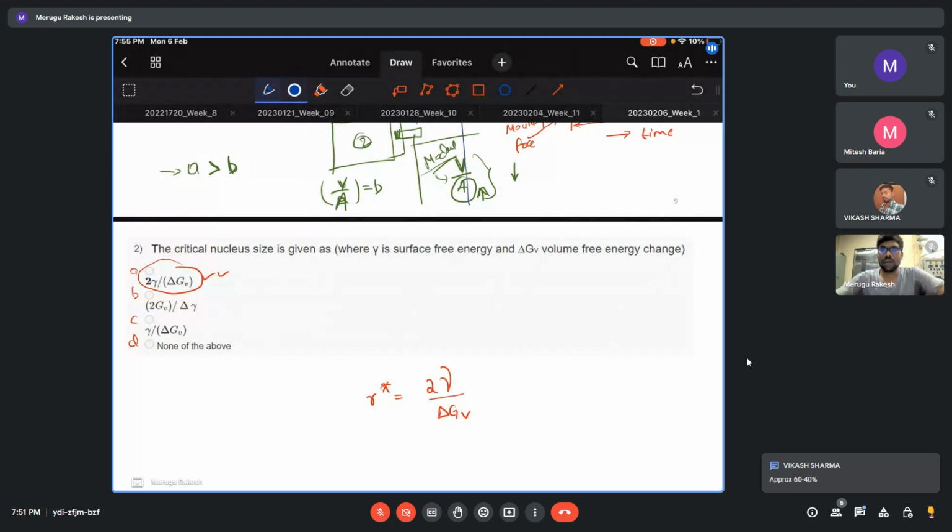Okay, 60 to 40%. In that case, you have several phases: alpha, beta, and beta prime also. So I don't know what microstructure they form. These phases will also influence the shape. If there are any literatures, you can search based on the microstructure and accordingly make out. There are so many things that influence the shape. We are mainly concentrating on the temperature gradient, but there is also the solute gradient, the composition gradient. These two factors play an important role in this discussion.